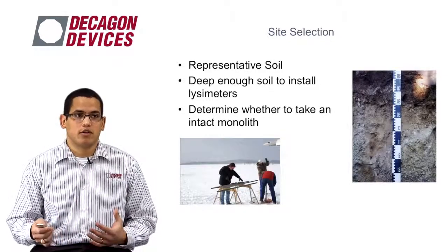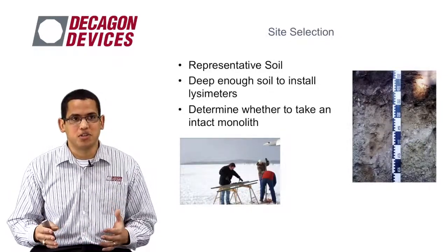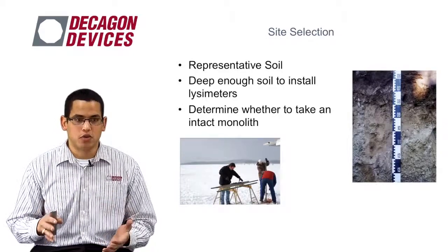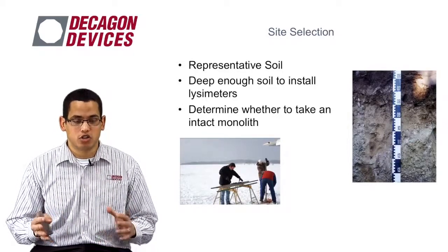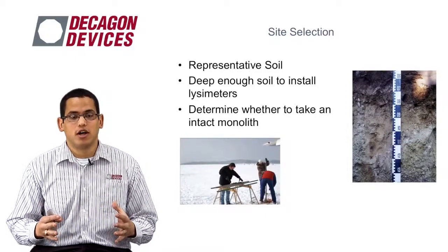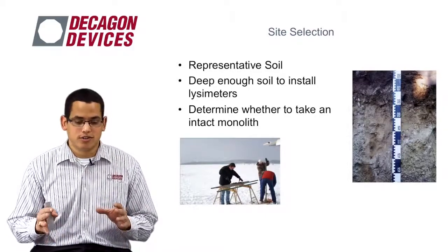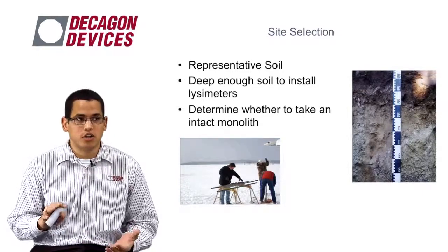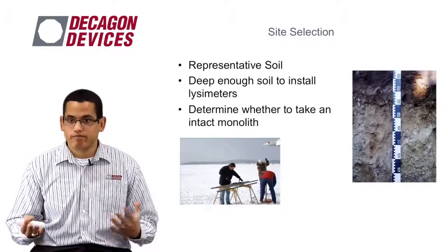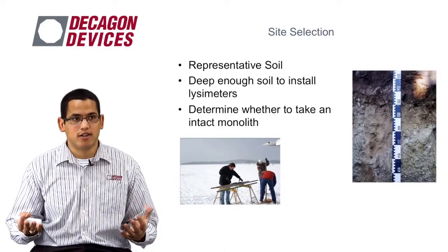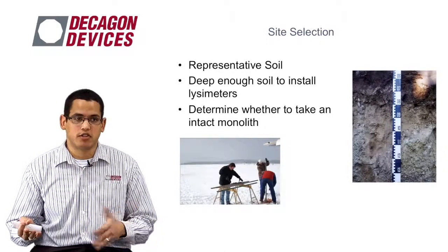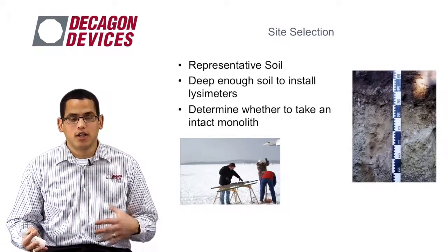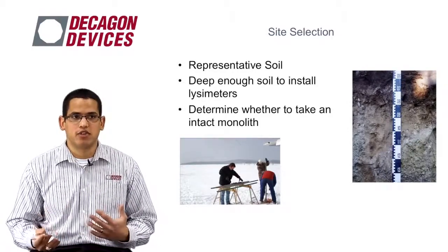It's also important that you have soil that is deep enough to install the lysimeter. If you have soil with shallow bedrock or just large gravel or cobbles shallow within the soil, a lysimeter might not be a very good tool on these sites, or at least not a tall lysimeter. You could go with a shorter 30 centimeter lysimeter and try to get an understanding there, or you can go with a repacked lysimeter, possibly, in these areas. But these are things that you have to think about.